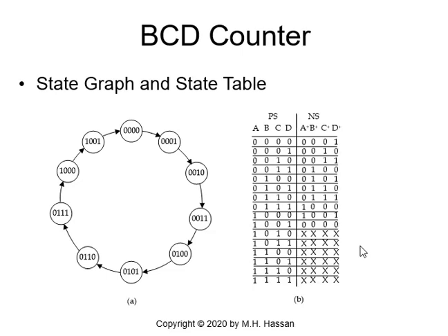I prefer to use don't cares, then test the counter, to analyze the counter and see what those don't care states end up to be. So for 1010, for instance, if you start there, at what state is it going to end up, and whether those don't cares generate a false circle or a false count for the counter and it may get trapped into another circle of states.